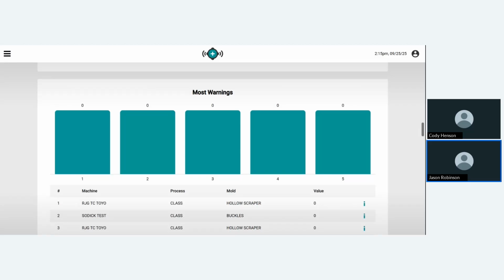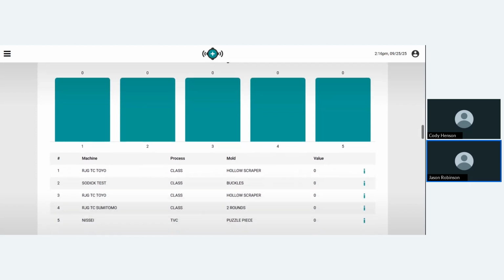So if your alarm lower limit is, let's say, 20 seconds and the high limit is 30 seconds, your warnings will be a little bit tighter than that. And warnings are like suspect. You're saying, okay, these might be bad. Maybe you don't throw them in the grinder or in the box that is all bad, but you don't want to put them in the green box where all the good parts are. You want to put them in some third location. The idea is, if you wanted to have someone go inspect those and see what condition the parts are in, you could. Typically, warnings will fire before they reject.